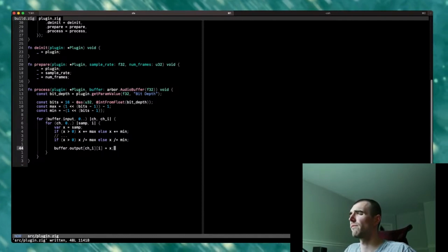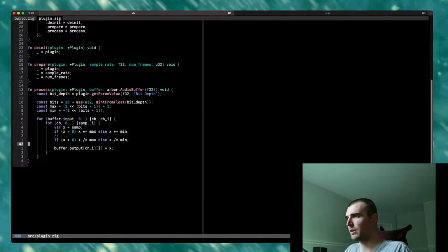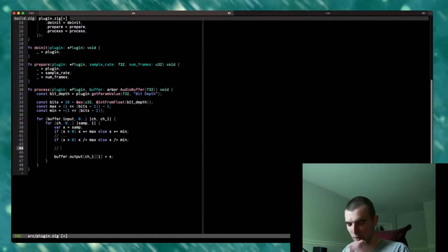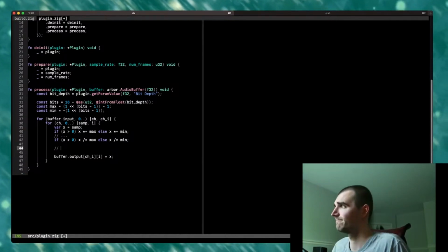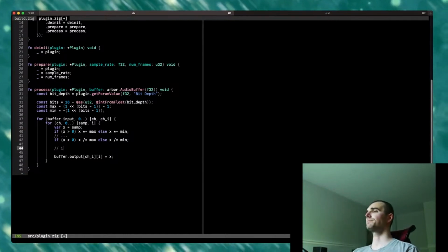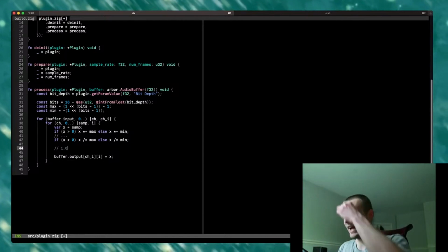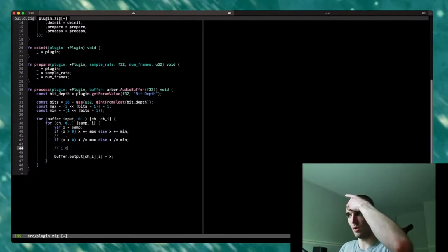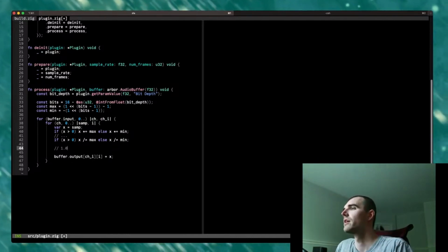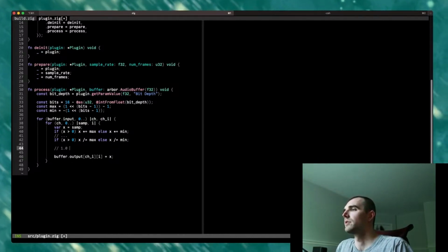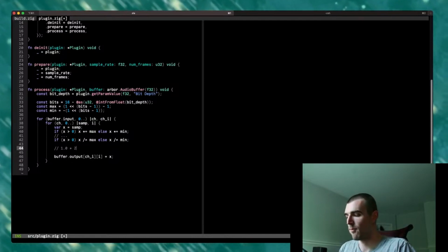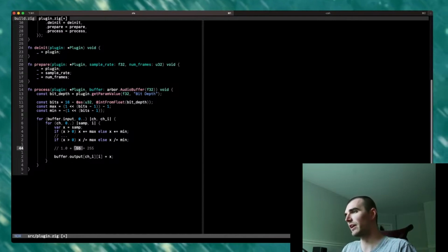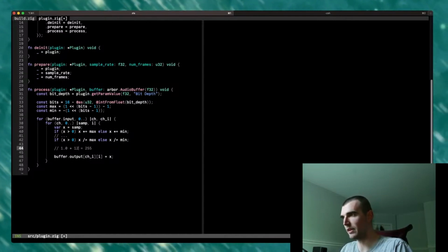Okay. Let me just do a quick little napkin math just to make sure this works out so I don't destroy the speakers. So let's say our loudest sample incoming is 1, and we multiply by 255. You get 255. Okay, we won't be doing that. We're going to be doing it by 127.